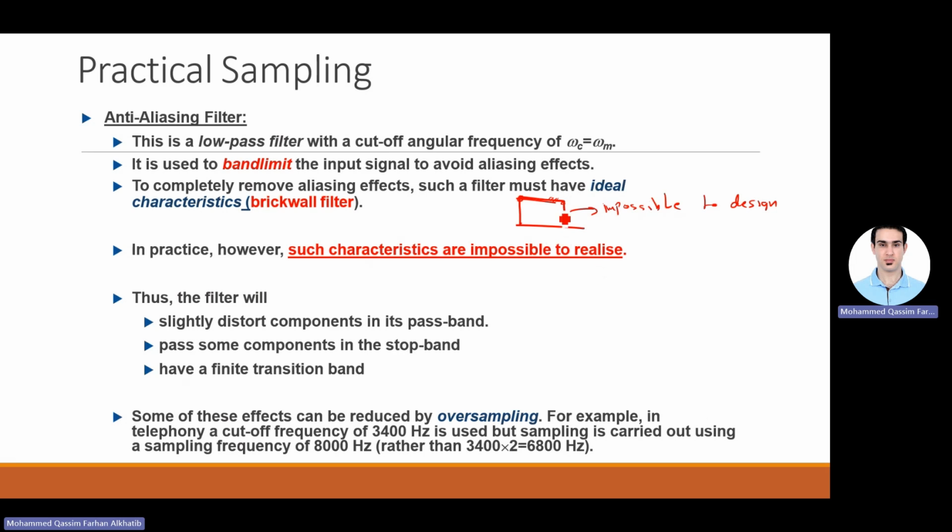We'll see later that no matter how sharp it is or how many coefficients we add into the filter, we will never have a perfectly flat response, and we will never have this sudden transition from 0 to 1. Usually filters will look like this. Let's assume this is the center. Or the best case scenario, something like this. And sometimes there's also what we call a ripple, some variation in the response at the peak.